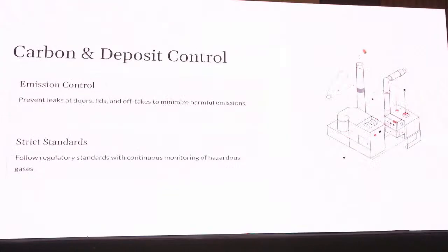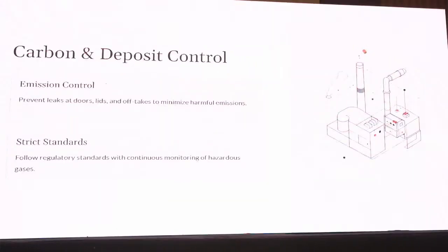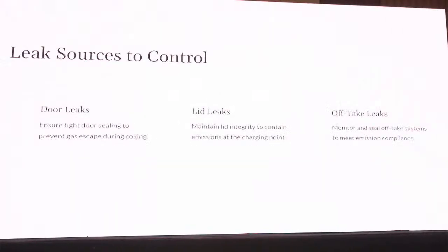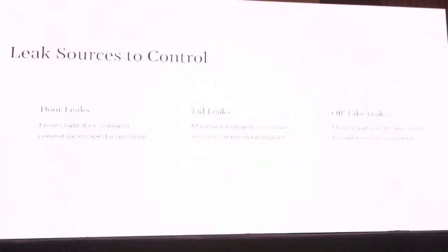Emissions control, preventing leaks from the doors, lids and offtakes, minimize emission. Strict standard continuous monitoring of hazard gases to be followed. Leak sources to be controlled. Leaks from the oven doors, charging lids and the offtakes to be controlled for emission compliance.